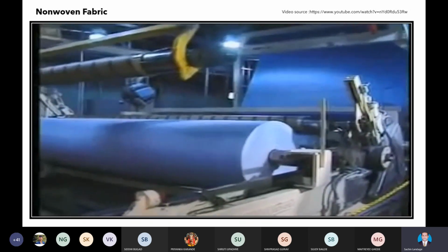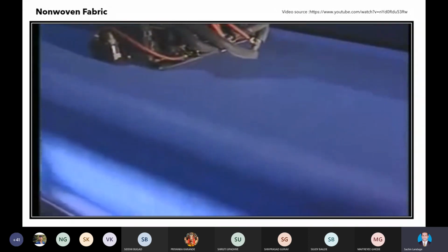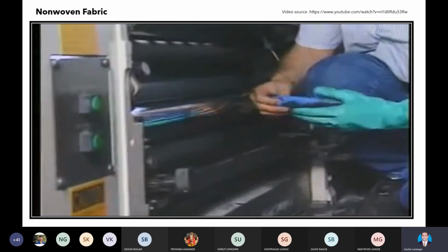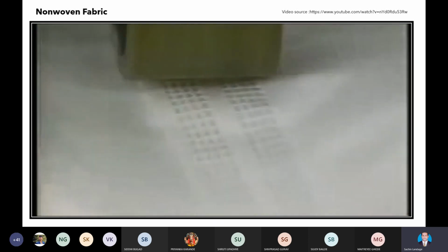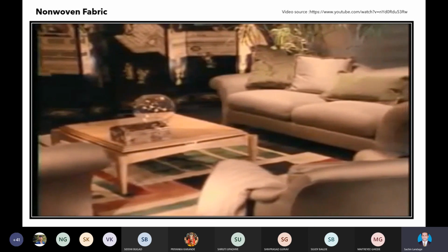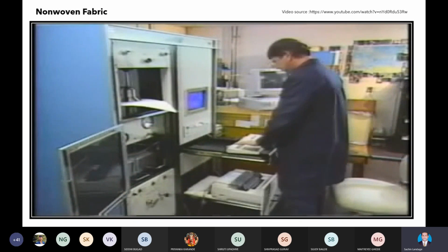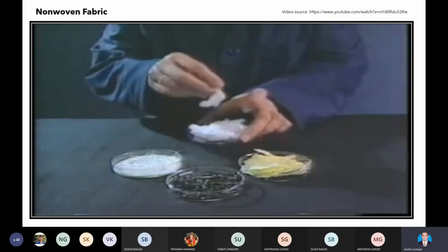While woven products can be produced at only a few feet per minute, non-wovens can be manufactured economically at 1,000 or more feet per minute. They are so inexpensive that they're cost-effective as single-use products, but they can be durable enough to last for years. They can be sewn, heat-sealed, punched, and cut in any direction. They can be used as replacements for traditional textiles in almost any application.